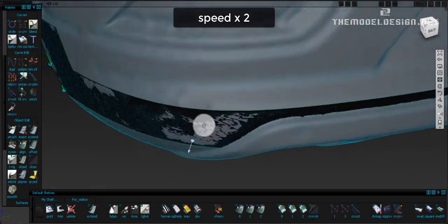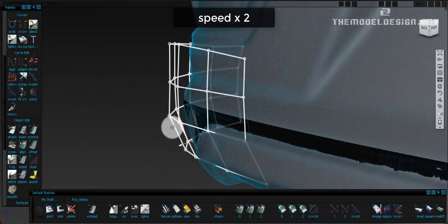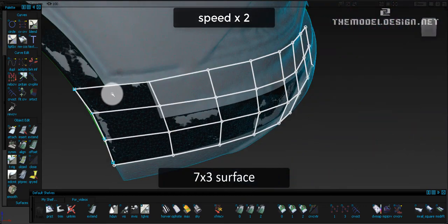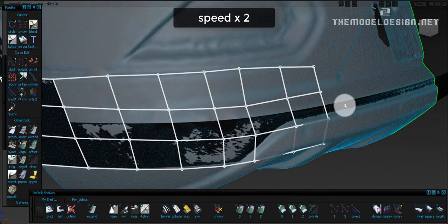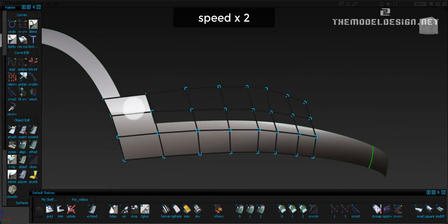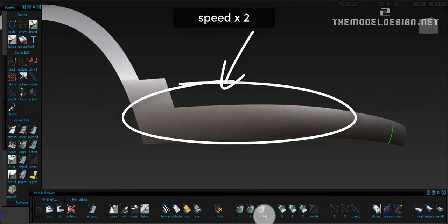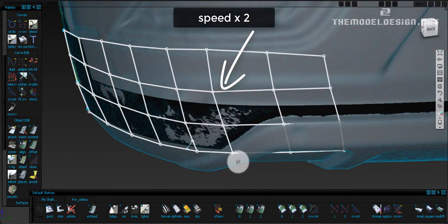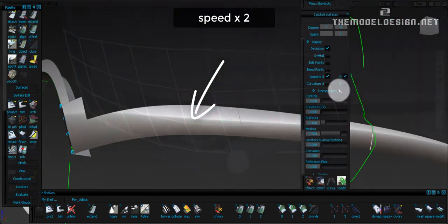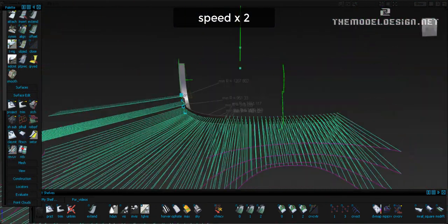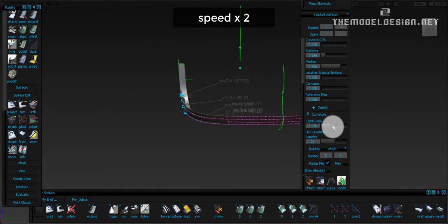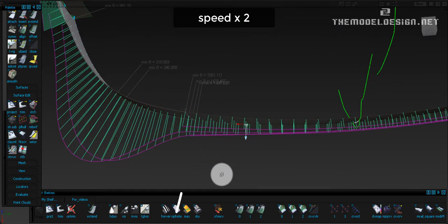So here is our surface after modifications. It is a pretty heavy 7-degree surface. It was important to have good highlights here. This area is a bit flat. In fact, we could push some of the CVs out, like this one or maybe that one. The comb curvature plot looks like this. There is some acceleration going on in here, which is what we wanted.